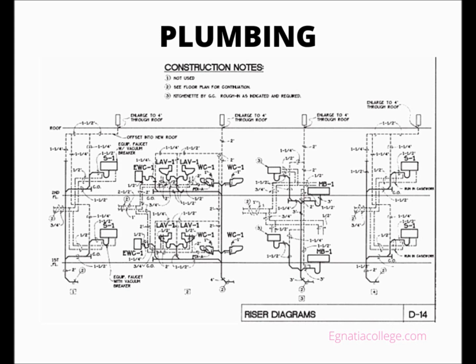Call-outs along the storm drain indicate the size of the pipe and its slope and give information about how the storm drain is to be coordinated with structural components of the building. On the first floor plumbing plan, the storm drain is represented by a heavy dashed line, indicating that it is below grade. Notice that the storm drain and the sanitary drain are separate systems. The storm drain only needs to carry rainwater away from the building. The sanitary drain must connect to a sewer or septic system.